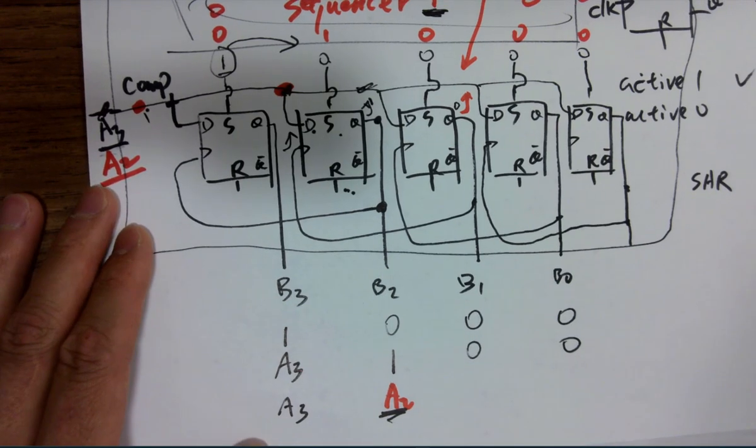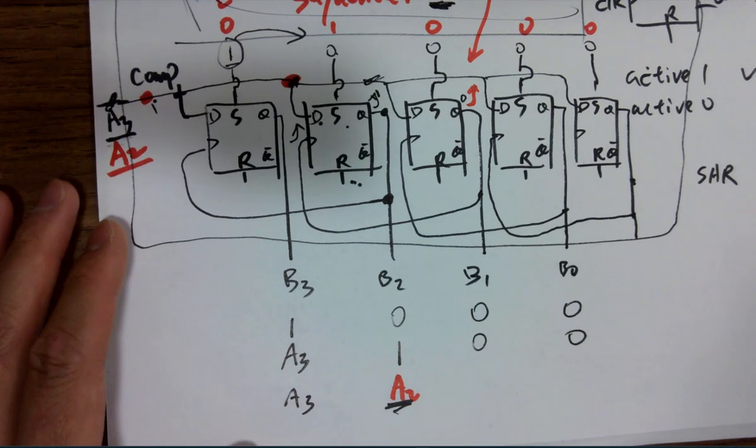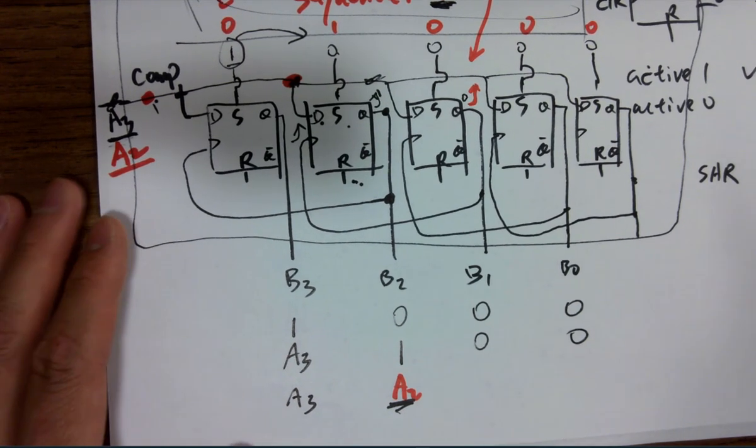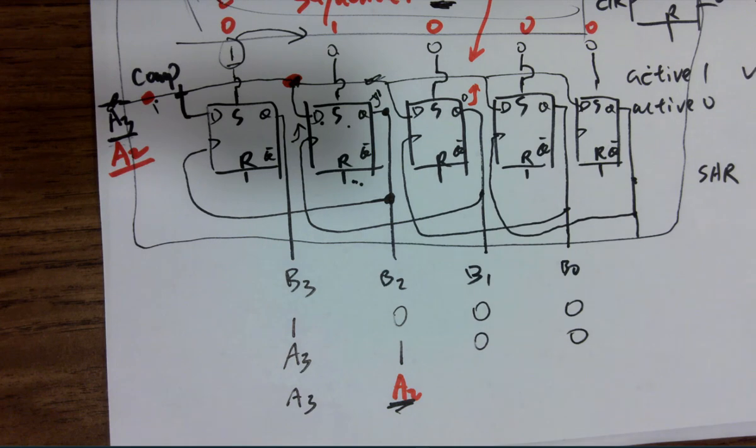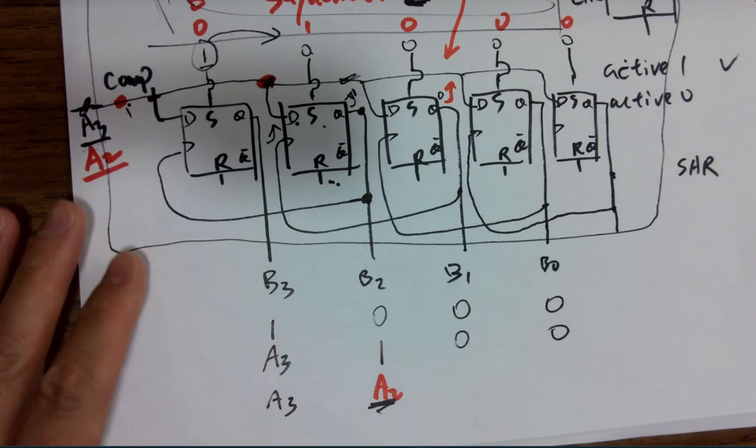Take a look. I want everyone to get the same concept here. Did you see that? Is there a rising edge? There won't be a rising edge. Either from 1 to 0 is a falling edge, or 1 to 1 there's no rising edge at all. Got that? Is that beautiful? Or, we designed the circuit just by chance and it works. Flip-flops are pretty cool. There's no rising edge, so A3 will be retained.